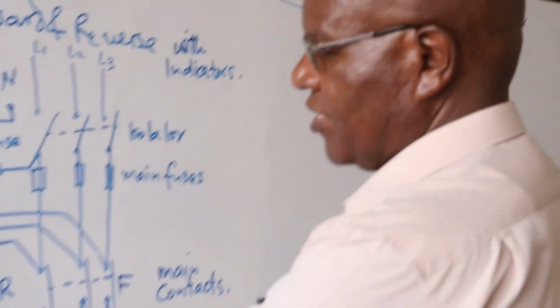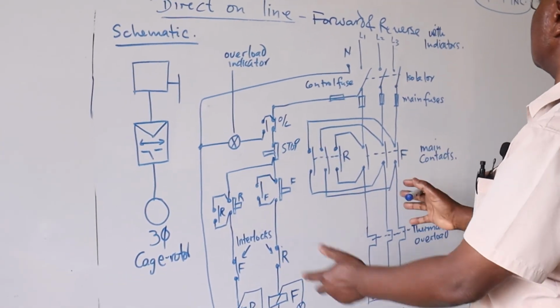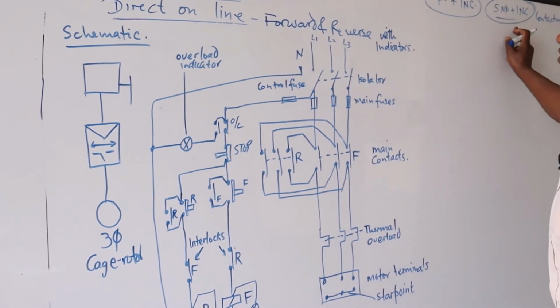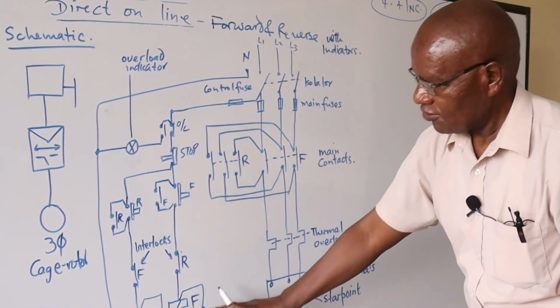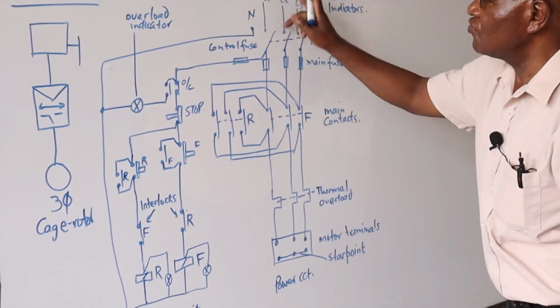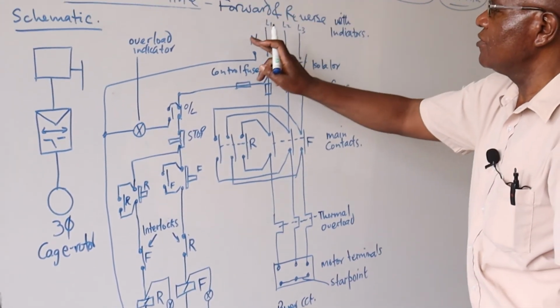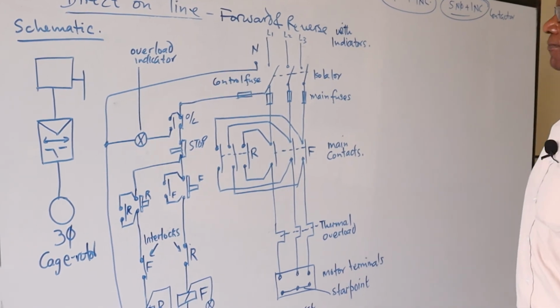So here I will need auxiliary contacts for these circuits here, or I go for another type of contactor with that kind of an arrangement. And of course, my contactor coils here operate on 240. As you can see, it's from live to the neutral.